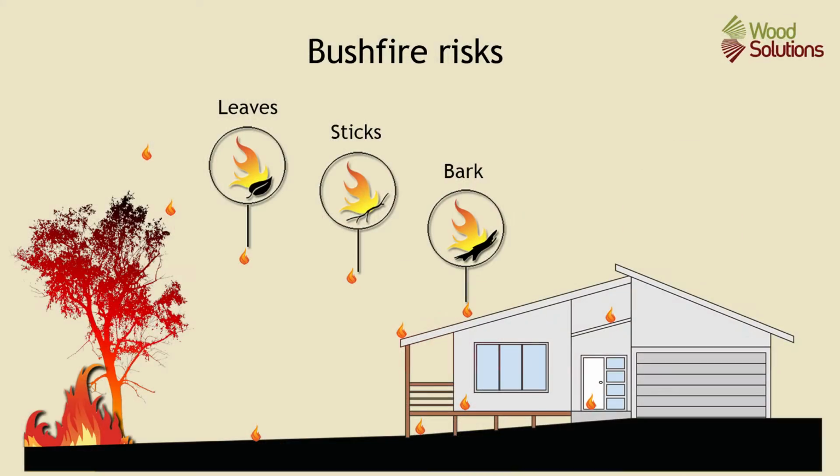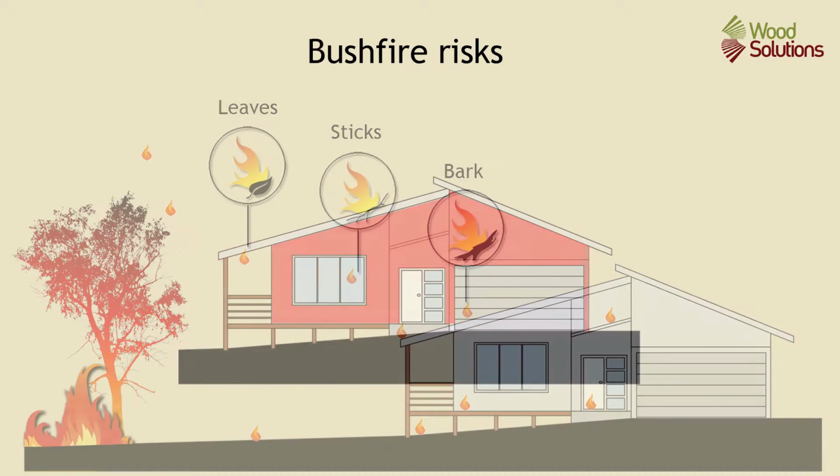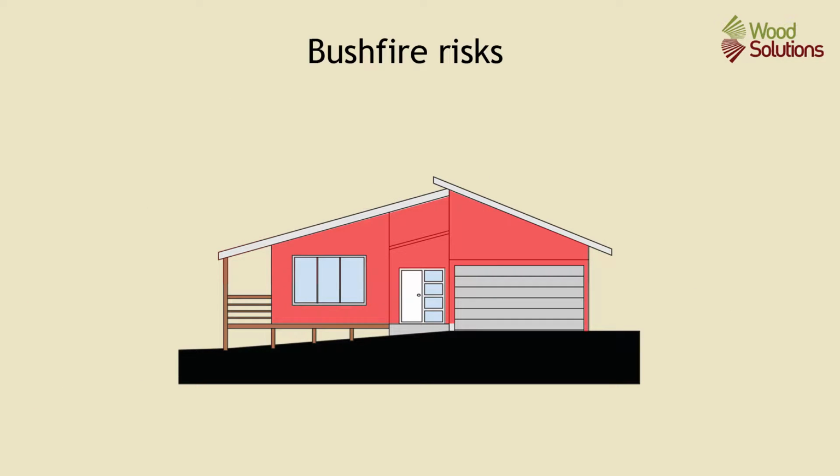The National Construction Code, or NCC, has specific requirements for buildings built in bushfire-prone areas. It requires compliance with AS 3959, construction of building in bushfire-prone areas. This standard sets out means to determine the bushfire attack level, or BAL rating, for the intended site. This sets the level of risk of significant damage from bushfire. The standard then establishes restrictions on the use of materials in the external envelope of the building and in decks. Restrictions increase with the assessed bushfire attack level, or BAL rating.